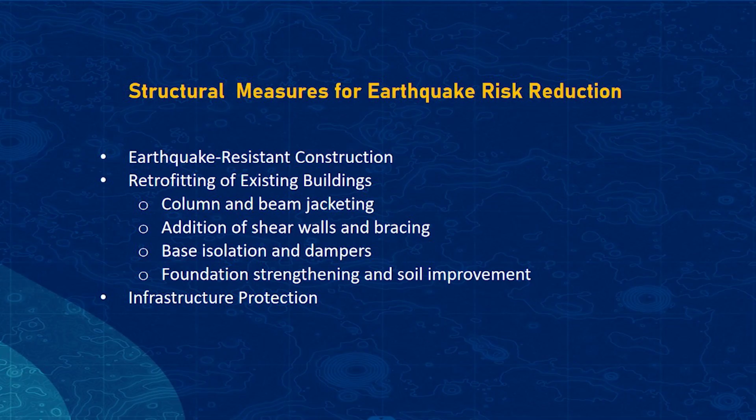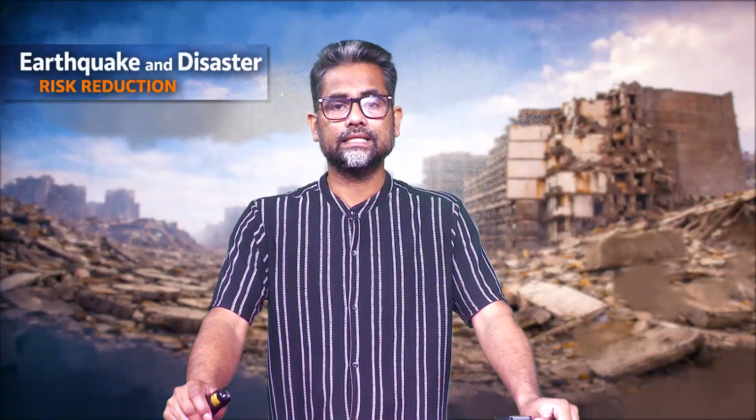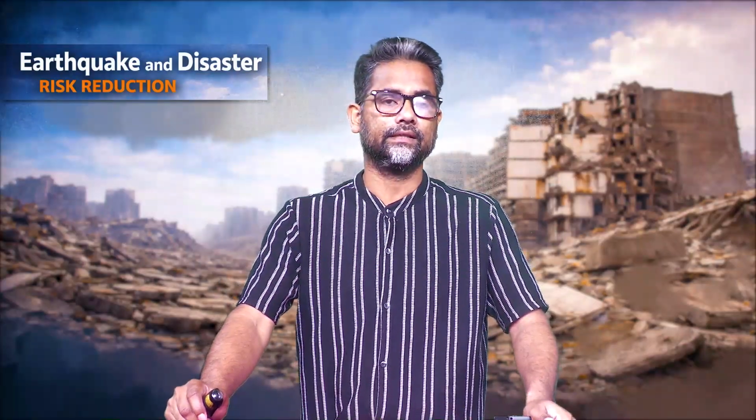First, earthquake resistant constructions. New buildings in zones 3, 4, and 5 must incorporate seismic resistant features such as reinforced concrete frames, shear walls, steel bracing systems, and flexible foundations. Lightweight roofing materials and elevated plinths help reduce structural mass and inertia force during shaking.